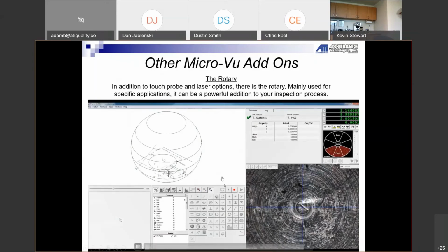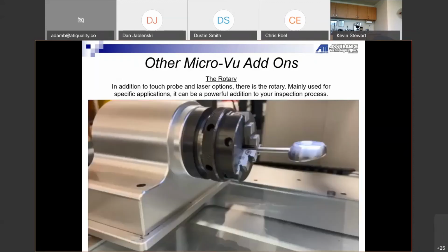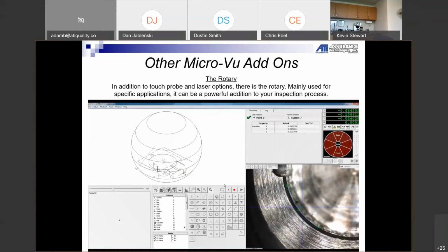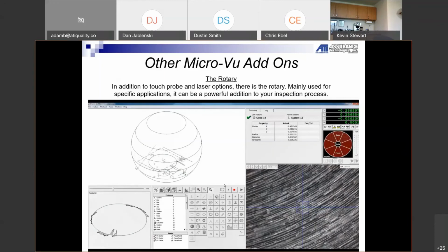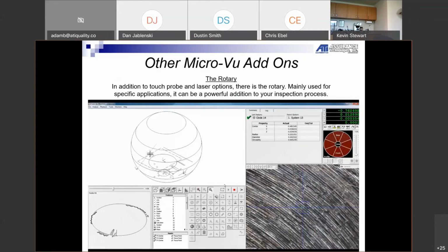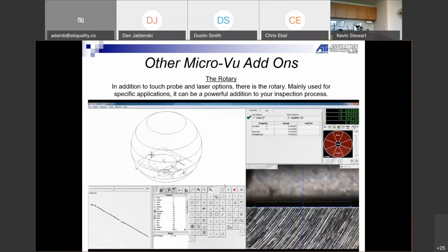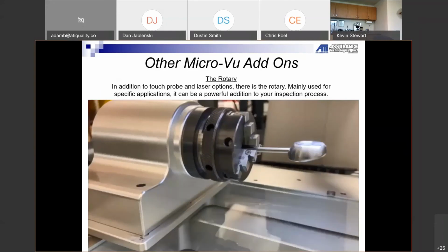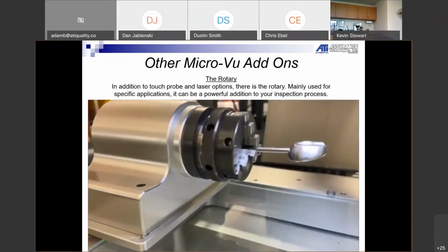I actually used the rotary, and you'll see me taking the measurements on this part, and then I took another video of the rotary measuring the part. So that first part that I did, I auto leveled to datum A, that top plane, so I know that my measurements are flat, parallel with the camera. So now I'm taking a more detailed version of my datum. So when I start doing true position, which was that little notch right there, and now this video is it moving around the machine, getting those measurements.